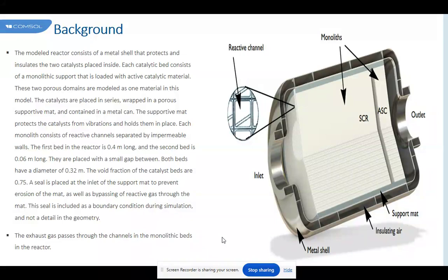The results may differ in other scenarios where the thermal effects of the chemical reactions are significant. What should be taken into account is that the space velocity is higher in the 400 per 6.5 substrate than in the 900 per 2.5, that is, it has a lower space-time. According to the data in the simulation, the increase in the space velocity when entering the substrate is 1.16 times higher in the 400 per 6.5 monolith than in the 900 per 2.5.